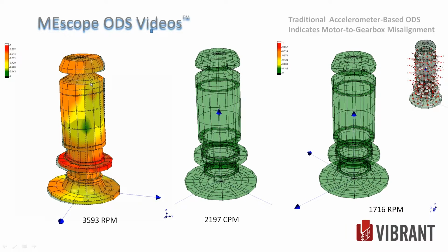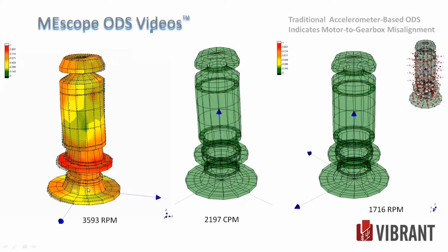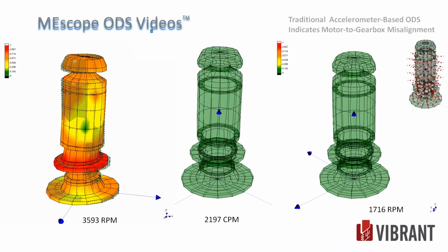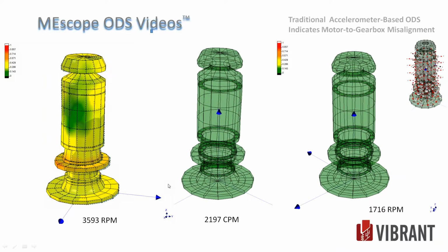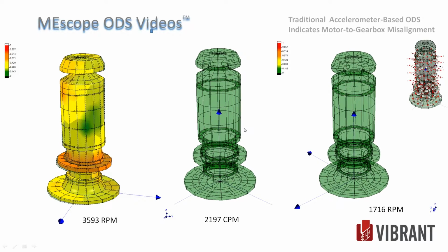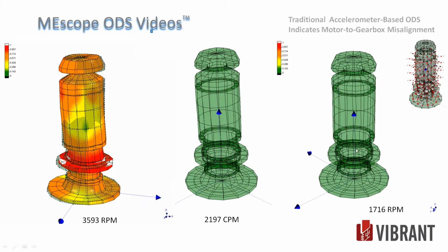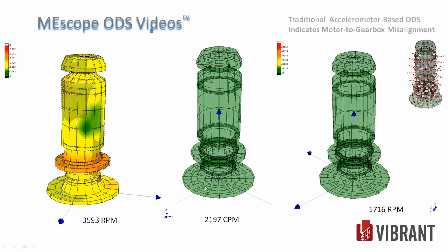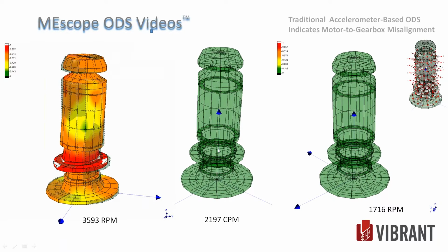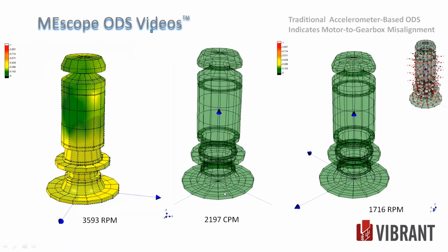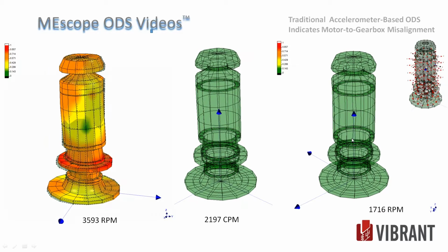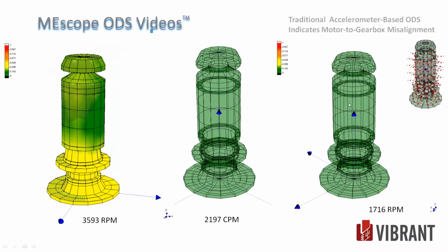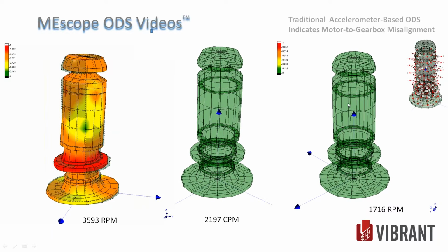They had to disassemble this a couple of times before they got it right, but there was something in the build that was causing this, some dimension that they weren't getting right. The other two, the rigid body modes, are right here. One of them is just, as you would think, the whole thing wobbling, but it's all in phase. Everything's a rigid body. This one, it's centered on the center line, but if you look at the top here, it's a torsional mode. It's twisting.